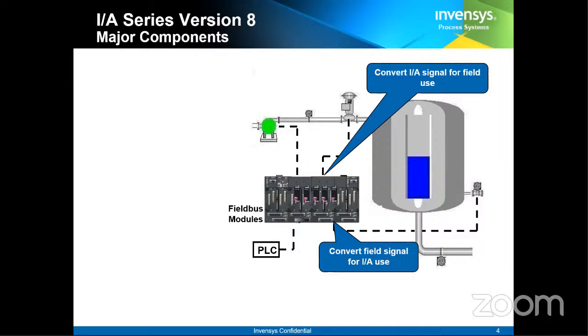The different types of transmitter, maybe pressure, flow, and not only different measuring types of transmitter, but also different protocols of transmitters. Like in a field, we may have a HART transmitter, or we may have Fieldbus transmitters. We have Profibus. These different transmitters ultimately do the same thing. The purpose of a transmitter is to sense the signal, but the communication protocol is different.